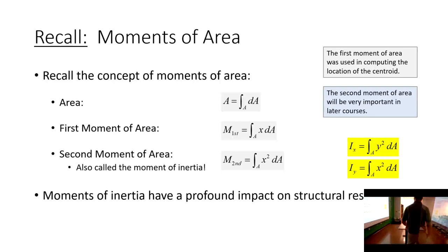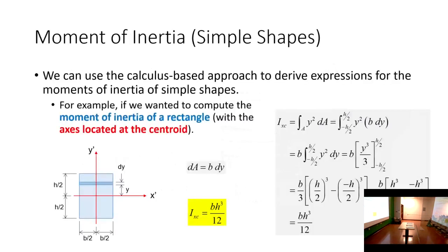And really the point of that assignment is I wanted you to understand that if there were references that you could use to look up moments of inertia for triangles or semicircles, or centroids for semicircles or triangles, that you understood where they came from. But what I want to do now is look at actually computing moments of inertia of composite shapes using the algorithm that I believe would be most useful and beneficial to you as an engineer, and that is through the use of the Parallel-Axis Theorem. And so the Parallel-Axis Theorem is really going to be the star of the show today.